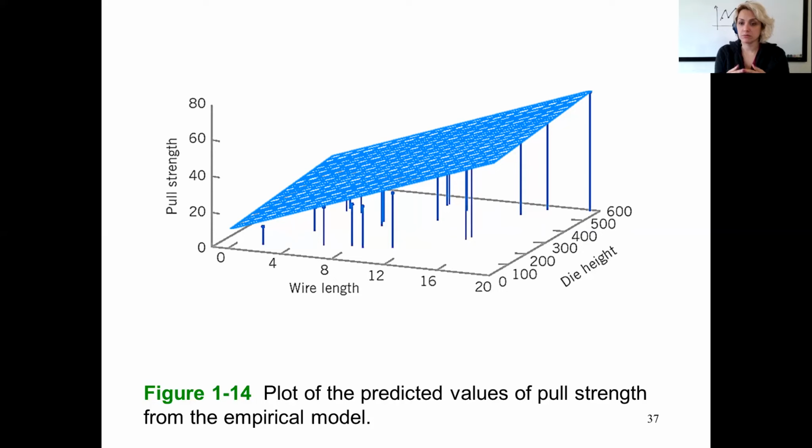You have 4 variables. You have a distillation column, and you want to know the purity of the methanol out of it. The purity of the methanol is my product. Then the number of trays that I have in my distillation column, one variable. The reboiler temperature, second variable. The condensate temperature. Now I have 4, even more than this one. Reflux ratio, the 5th one. So it's like that. What about 5 dimensions?